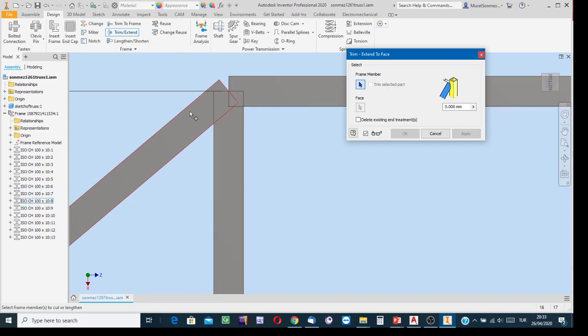similarly, if you are going to need to have space to allow the welder to position the electrode between them, a certain empty space is needed, then write it into this box. In this exercise, say that 5 mm space is sufficient. Or depending on the size of the point of the electrode, see the diameter of the electrode and then at minimum write the diameter of the electrode into this box. 5, let's say. And then,